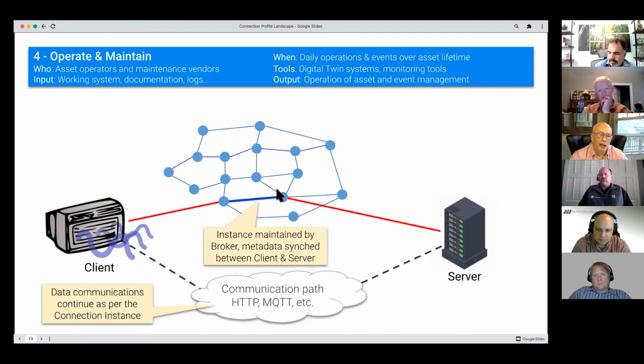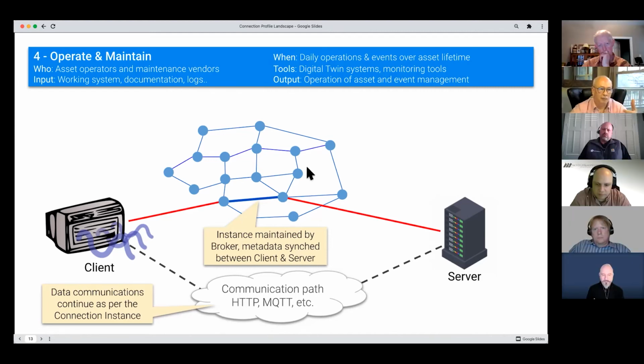There is no reason why any node can't communicate with any other node, as long as they have compatible connection profiles, and as long as they have a contextual reason to communicate. Right, so there needs to be a contextual reason, either in the same building or in the same plant room or whatever the case is, and they have to have a compatible profile. As long as they have those two, they're good to go. They would understand whether the data they require is available on an alternate path. They should be self-aware at that point. Well, the awareness is sort of one hop, but through that, you can build multiple hops. Okay.